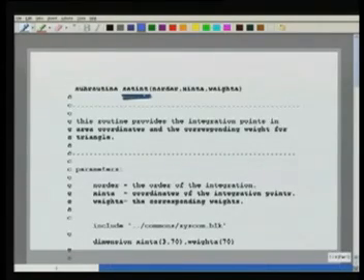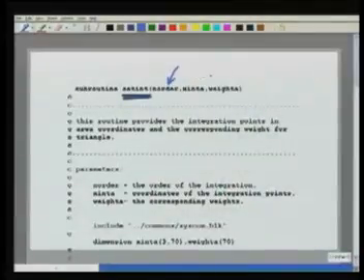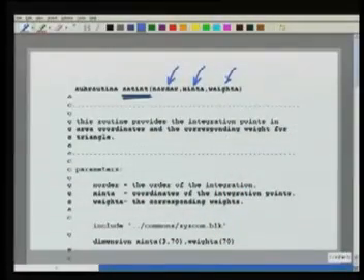which, what does it do? You input to it the order of the integrand. The order of the integrand we have to compute from the integral, the terms involved in the integral, exactly the way we had done in the 1D case. One has to go and find this order. Given the order of the integrand, it returns the coordinates of the integration points for this particular order and the corresponding weights.